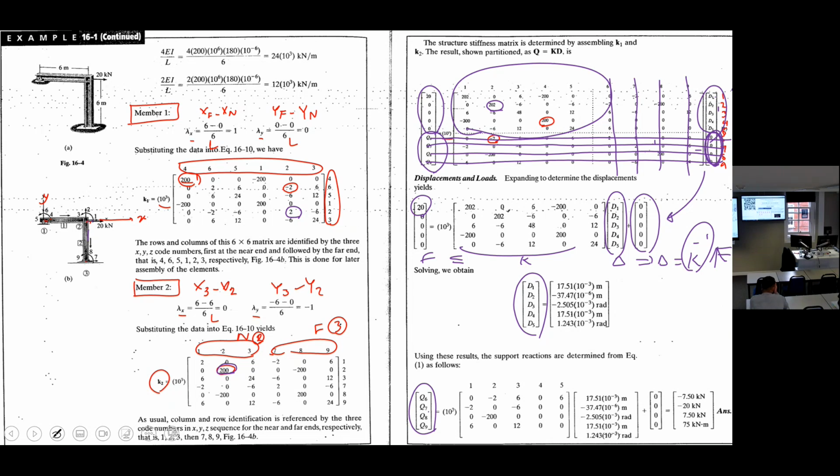In terms of matrix notation, it's like multiplying this part of the elimination by this part, because this part will be multiplied by this part, which is 0. If you multiply this 4 by 5 by this 5 by 1, you will get 4 by 1 and your support reactions. If you don't like the matrix notation, just go for individual calculation of Q6, this line multiplied by this line. Right? So this is how we calculate support reactions.